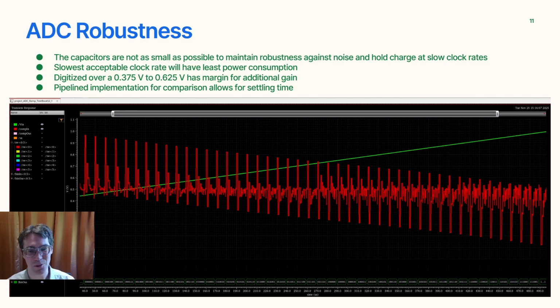The graph really shows you the whole process of converting and how the comparison switches from finding the most significant bit needing to be held on to, then it becomes a negative comparison as you get past the midpoint.